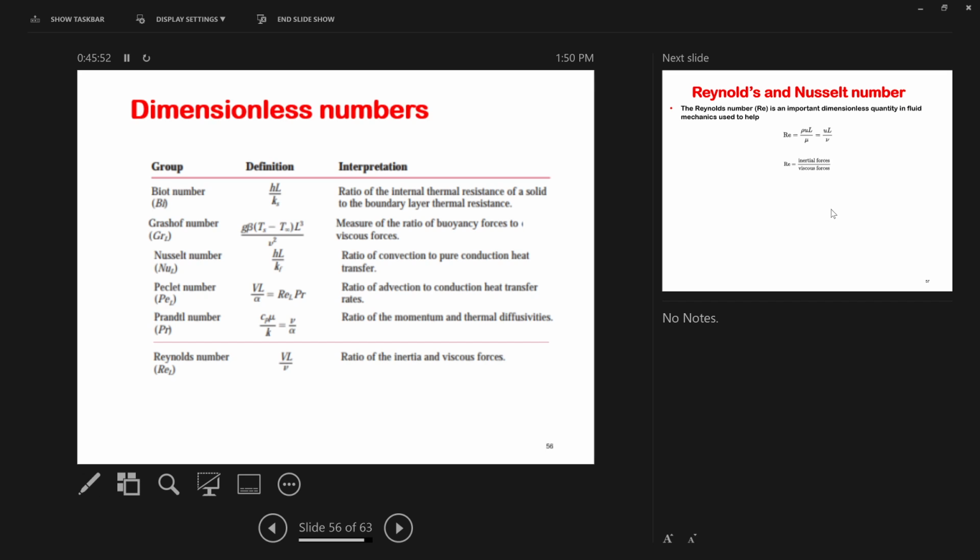That's where the Biot number comes in. You're essentially comparing the heat transfer coefficient, the convective power of your system, to the conductive power of the solid, right? So heat transfer coefficient multiplied by the length of the system, divided by the conductivity. And we are assuming the conduction happens so fast that the temperature of the solid is going to be uniform all throughout, which means that your conductivity is much, much stronger than the convection because it happens so much faster.